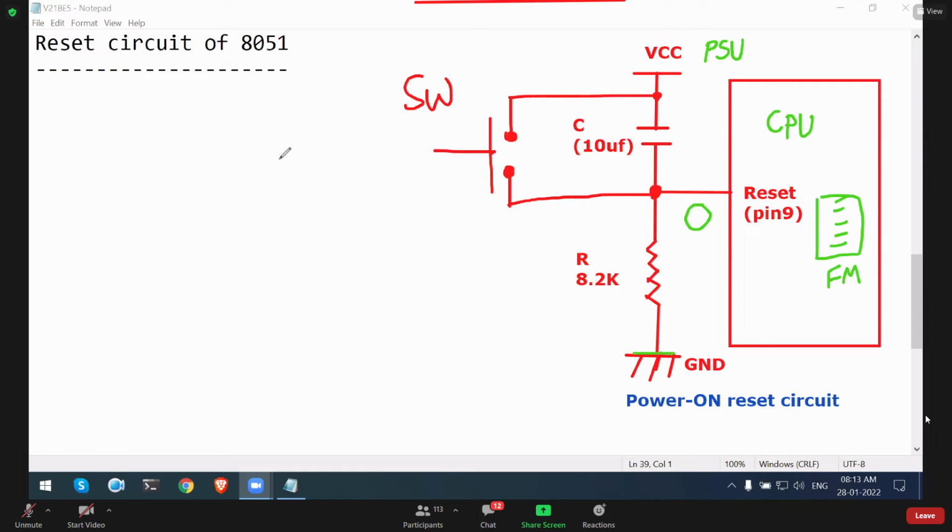No, PWM signals are not given to reset the microcontroller. PWM signals are totally different. PWM signals are not used to reset the microcontroller. It is just pure 5 volts that will be given to reset the microcontroller. In PWM, your voltage will vary.